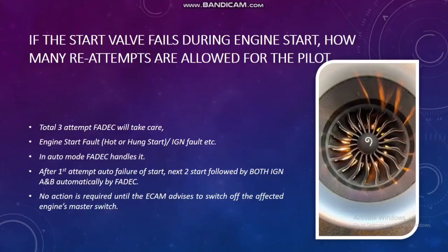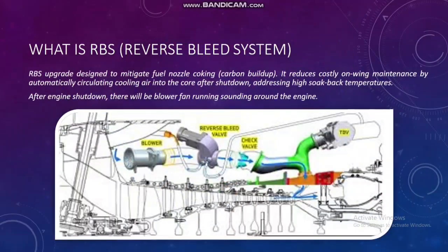In case the valve is stuck, in the open or closed condition, then you have to go with another procedure for manual opening of the valve for starting purposes. So no action is required unless ECAM advises to switch off the affected engine master switch. During this procedure, no action is required unless ECAM is giving some indication.